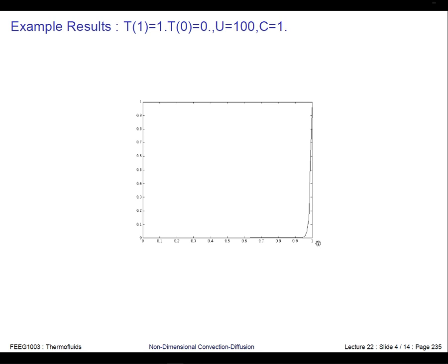And there's only a tiny bit of diffusion in the domain, but that diffusion is actually quite strong because this gradient is really sharp. Okay, but it just can't penetrate very much into the fluid because the convective strength of the energy transport is so strong.